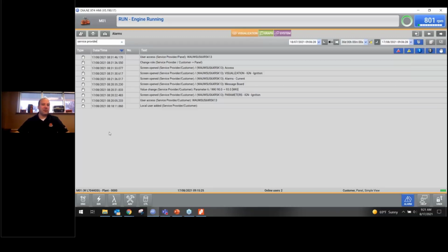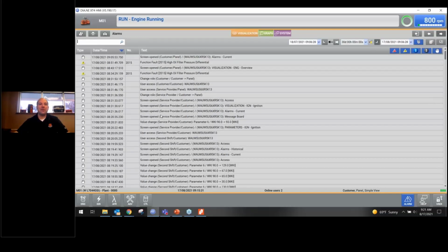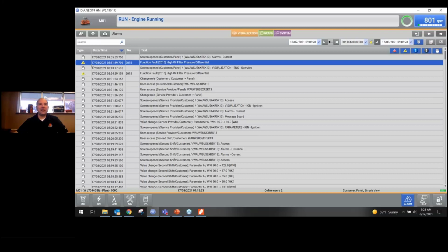Now, as I step forward a little bit from there, I'm going to clear this out again because I want to start doing a little bit of eHelp. As I look at my fault here, again, it gives me my time and date stamp. It also tells me which particular fault it was. Now with ESP, it just said, hey, I've got this code, go and dig into eHelp. Well, this one, instead of just looking at flashy blinky lights, says this is a high oil pressure differential that we are having to troubleshoot. And this is a functional fault, so saying that it's outside of its range, or that we're beyond where we want it to be to say that the engine is running correctly.